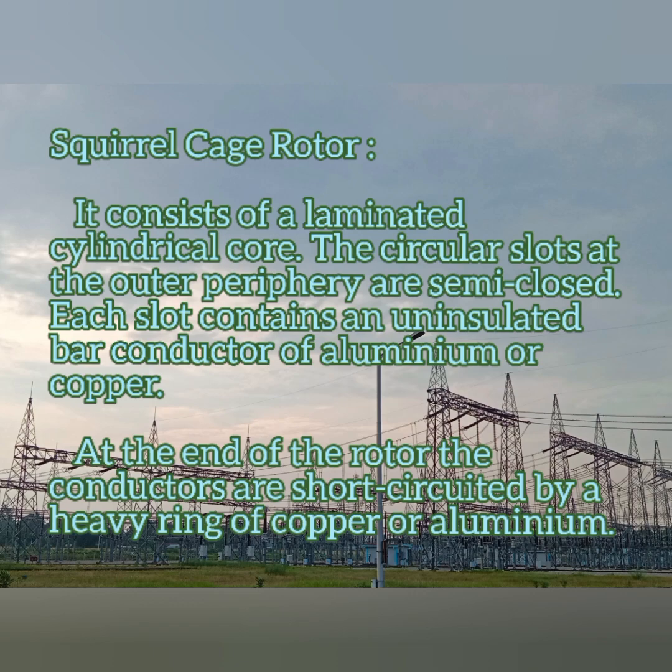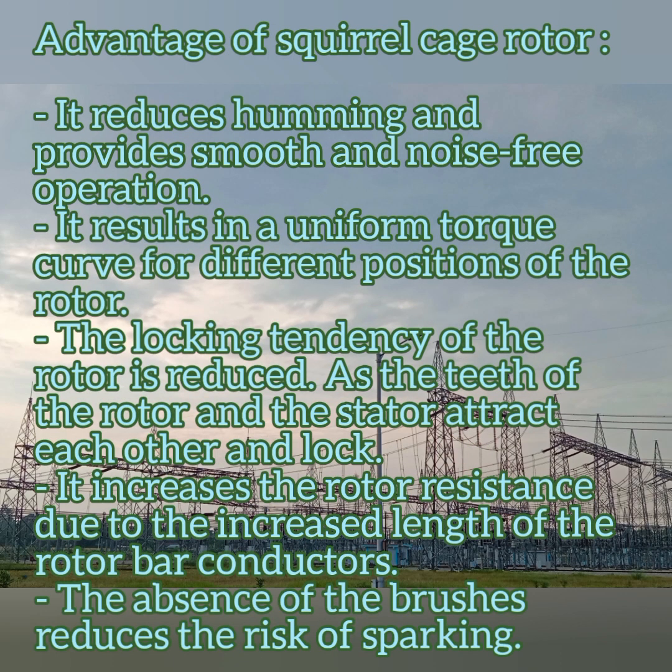So the main advantage is that it reduces the humming, which means noise and sound, and provides a smooth and noise free operation. It results in a uniform torque, which means the torque will be split uniformly overall, because the squirrel cage construction is also like a full cylindrical structure.